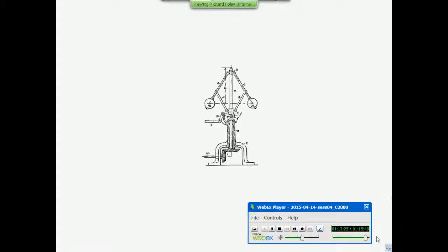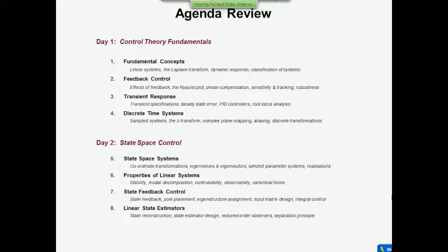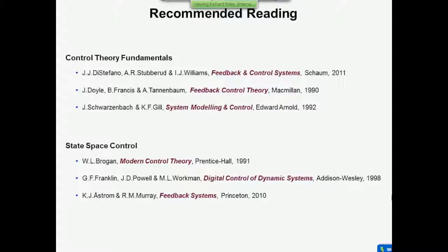Right, so for stability, you're looking for poles in the stable region. For robustness, it is not simple. It really is not. The techniques get much more complicated when the systems are multivariable, and they're well outside the scope of what I can do here, I'm afraid. For single input, single output systems, there are some nice graphical techniques in the second book that I recommended from the first day, the Doyle, Francis, and Tannenbaum book.